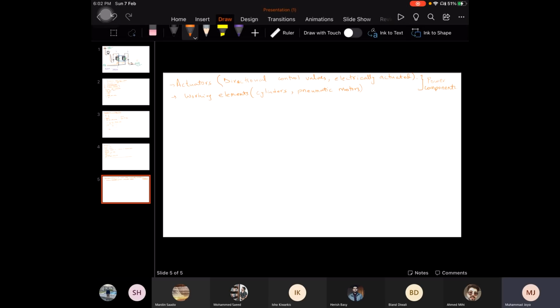For a pneumatic control system, the control is achieved by pneumatic components such as various types of valves, air distribution routers, and sequencers, etc. For an electro-pneumatic control system, the signal control element is designed with electrical components like electrical push buttons, switches, proximity switches, and later on we'll also be studying programmable logic controllers. I hope that you understand this.